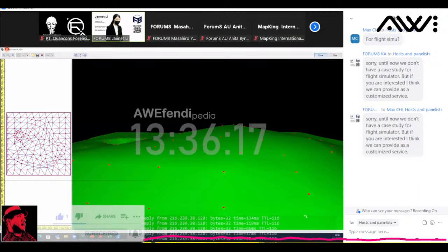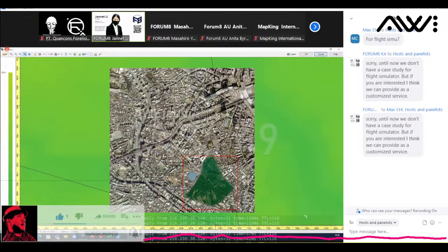Now we're going to try to make a road inside this space. Go into edit and then plan view, and then just magnify this area again. According to page 21, we're going to build a road with 3 points from 1 to 3. There are 2 types: make road and make road spline. We're going to use make road. 1, 2, and 3, and just right click, finish road.